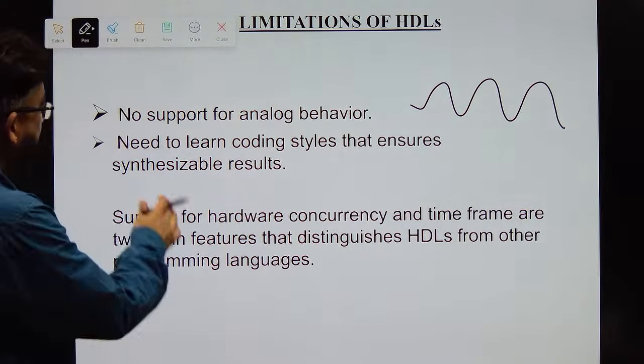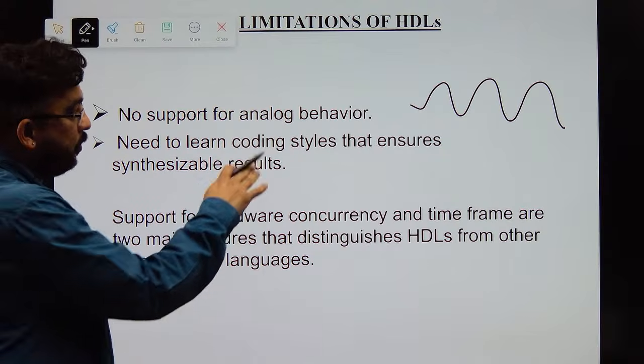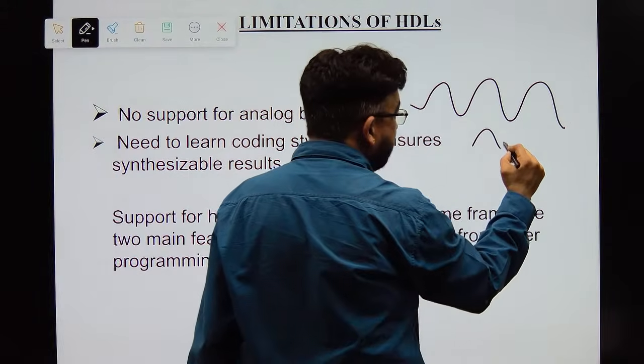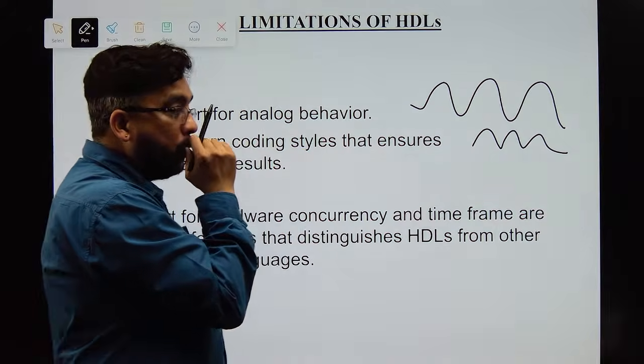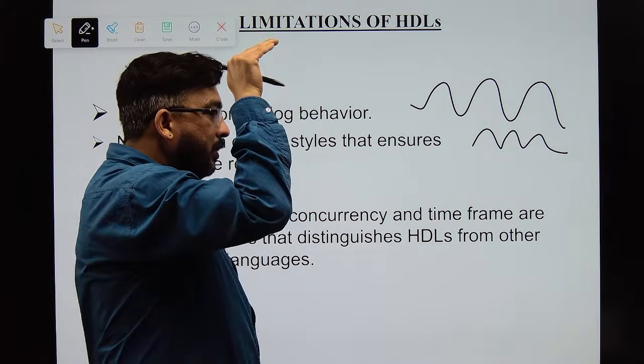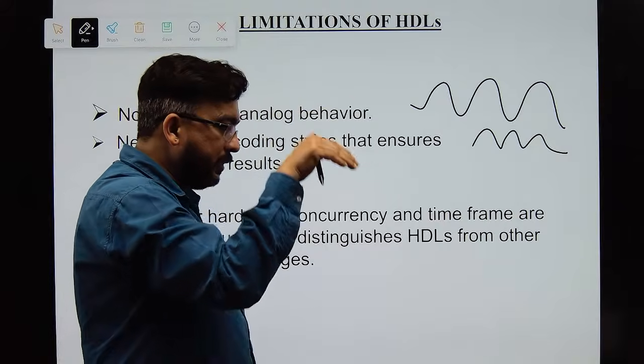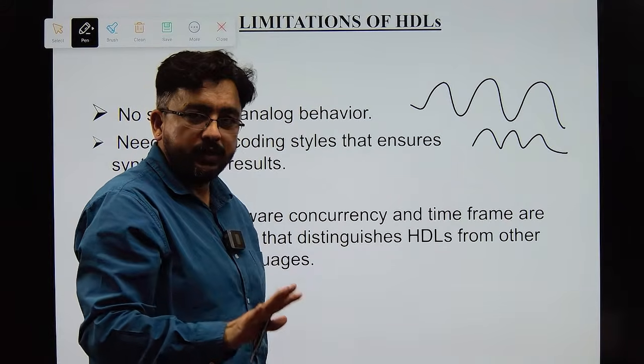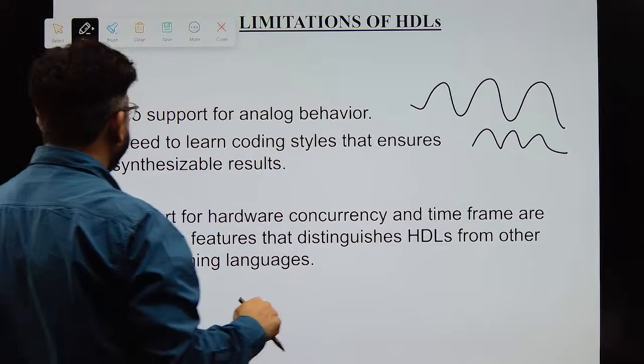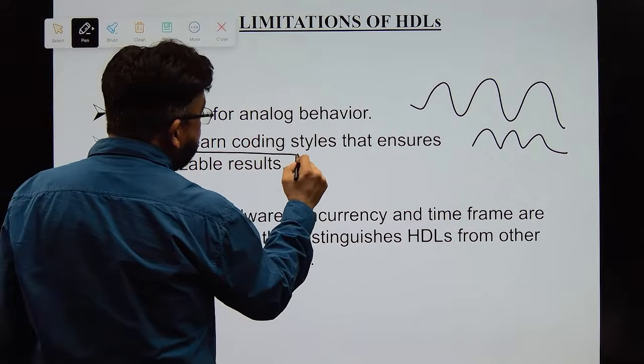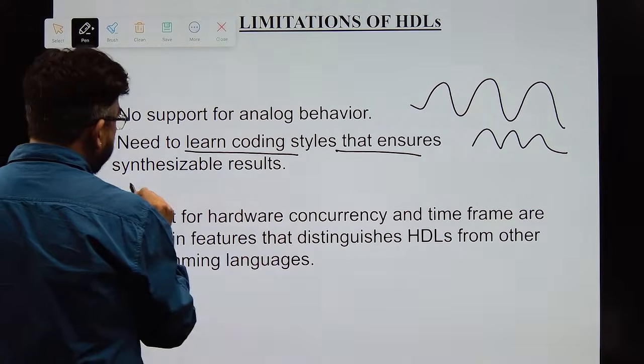That line means no support for analog behavior or output like this. Basically, this logic is going inside the FPGAs, and an FPGA is a purely digital device. You need to learn the coding styles that ensure a synthesizable result.